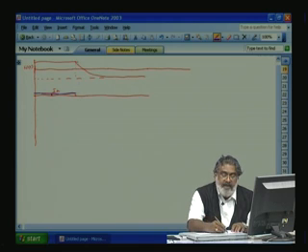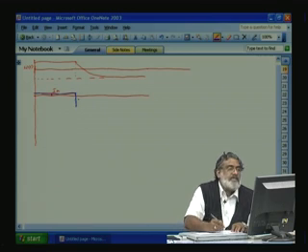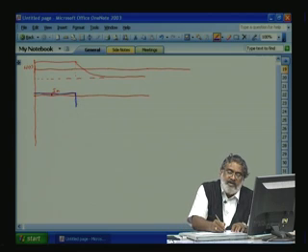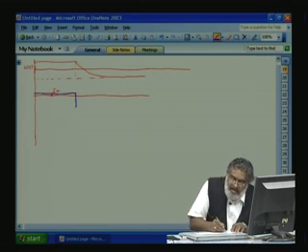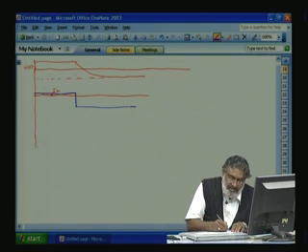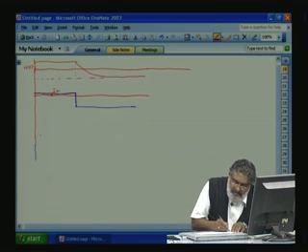So, quickly compared to the mechanical time constant, this will come to the maximum rated current, IA maximum, here. If you expand this, it will go with a first order lag depending on the electrical time constant. But with respect to the mechanical time constant, this is fast and it will come there and the current will stay there till the machine reaches that speed. When the machine reaches that speed, let us see, we are controlling the armature voltage. So, let armature voltage and back EMF be on this axis.